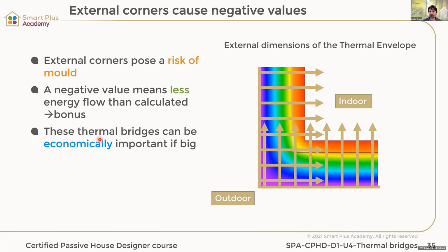Then option one, that we're not entering negative thermal bridges smaller than 0.01 watt per meter Kelvin into the thermal bridge calculation, is not working any longer, because from an economic point of view, we're now over-designing our building envelope. It could be not economical any longer, especially in a really big, tight project, and that could be a thing to improve the performance. But normally I wouldn't do it. It's just a bit more safety in my calculations and gives me a bit more security.